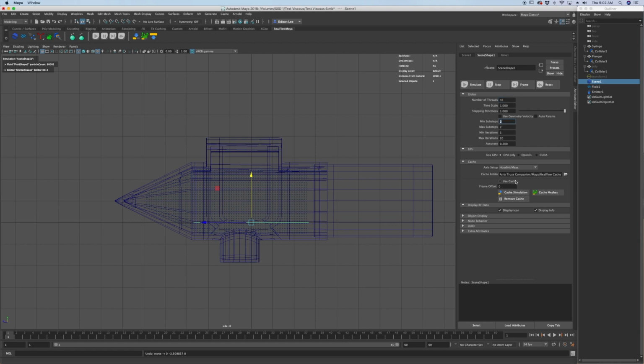Here I'm going to go from 2 to 10, and I'm going to set max substeps also to 10, so it's sort of an absolute number. Iterations, I'm going to go for 60 and 60. I'm not going to go into details on these parts just yet in this video. This is more just to see how well RealFlow performs under these conditions.